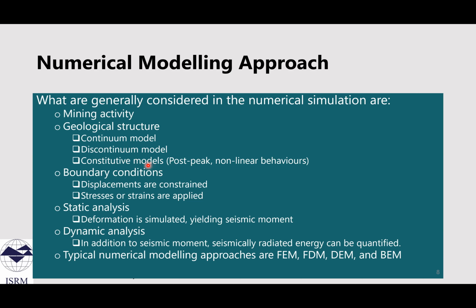If there is a large difference between this numerical analysis and field measurement, we need to modify this numerical model, or even change the simulation method. So this is a kind of back analysis to calibrate the parameters and numerical modeling method.